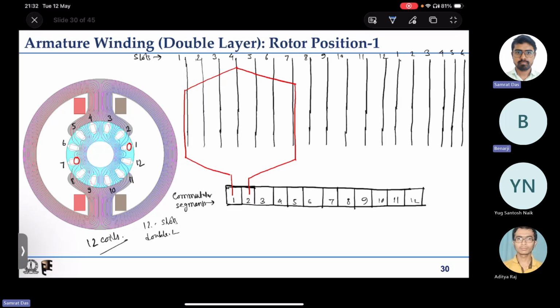They place copper bars in the rotor slots, and later use welding with the help of copper to connect one conductor with the other conductor in another slot to form a coil. That must be a quite high power machine, a big machine. Yes, sir, exactly, that is the case.